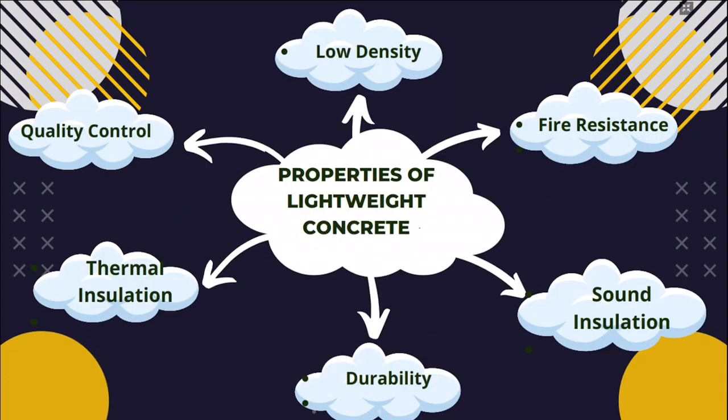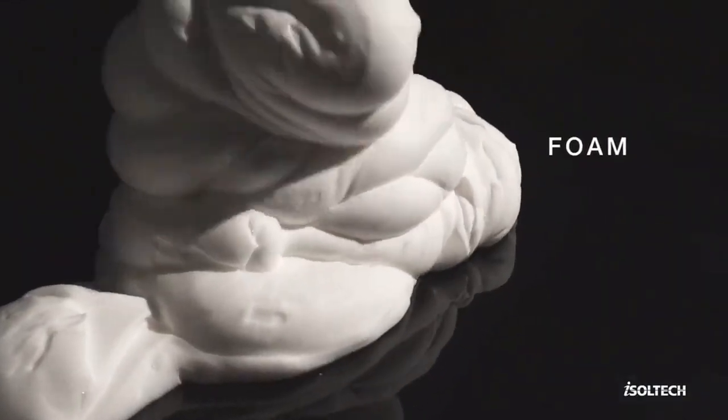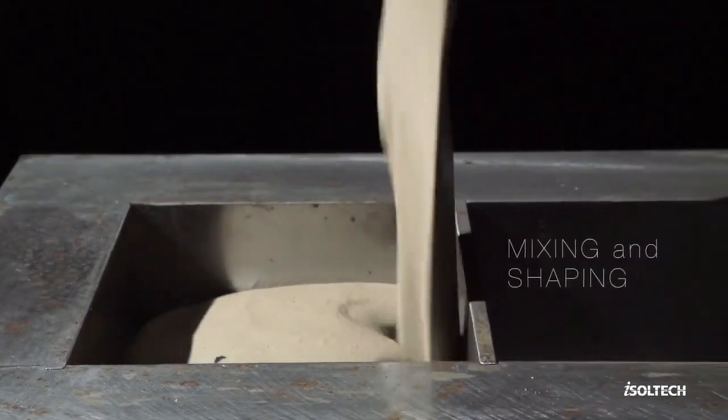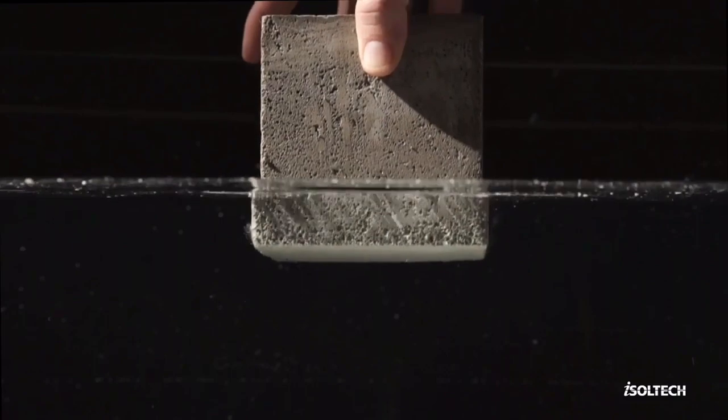There are several properties of lightweight concrete, among them low density, fire resistance, sound insulation, durability, thermal insulation, and quality control. Low density: the density of the concrete varies from 300 to 1840 kg per cubic meter. The lightest grade is suited for insulation purposes, while the heavier grade with adequate strength is suited for structural applications.